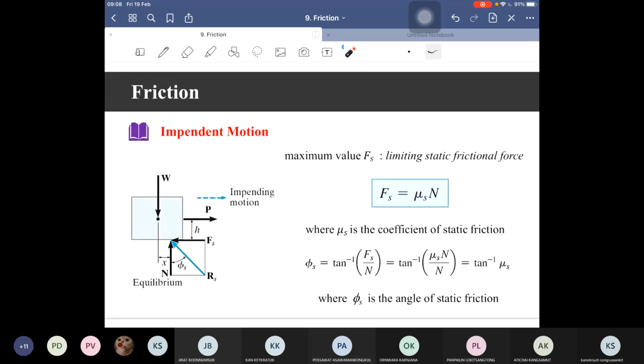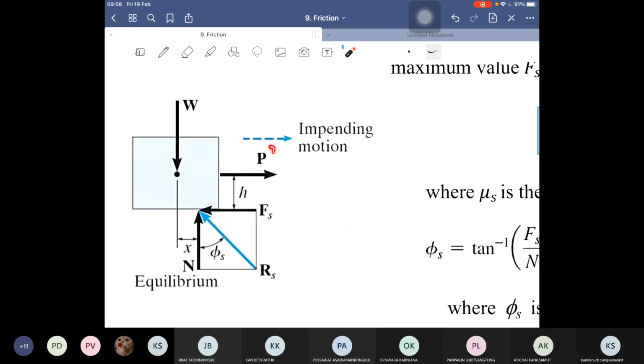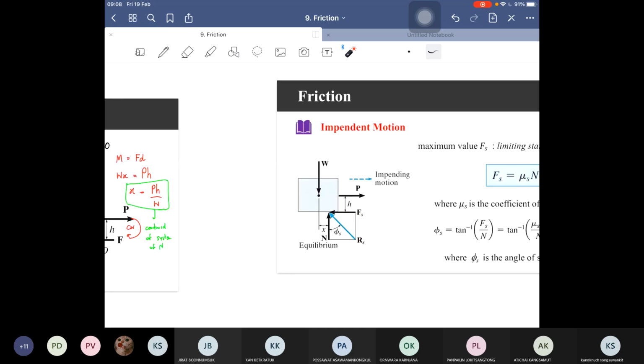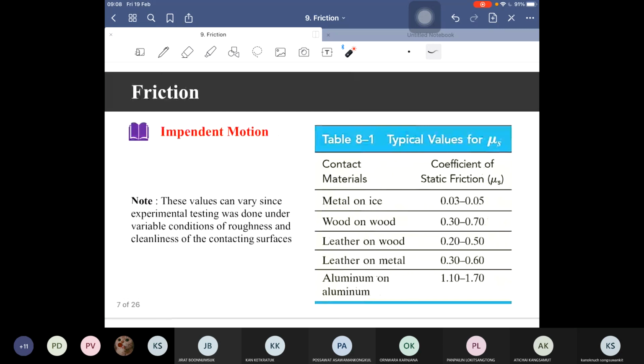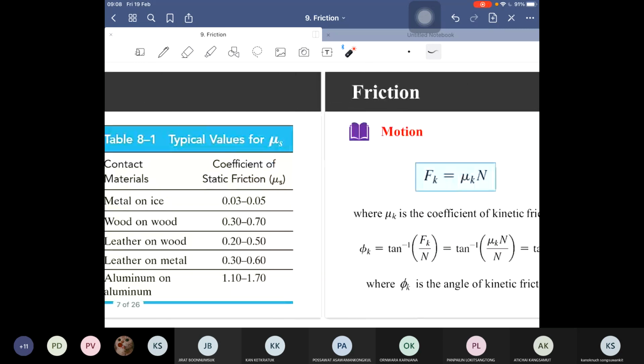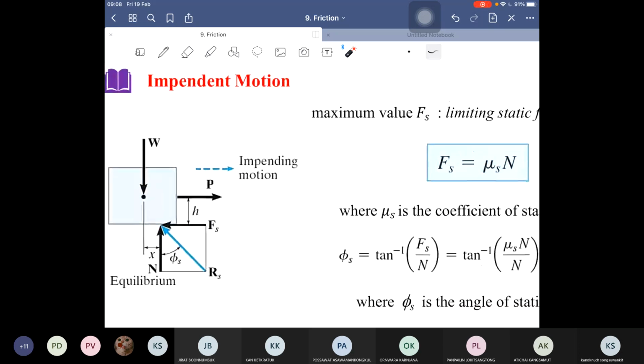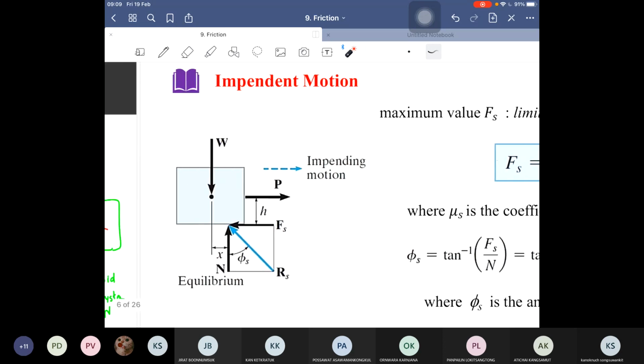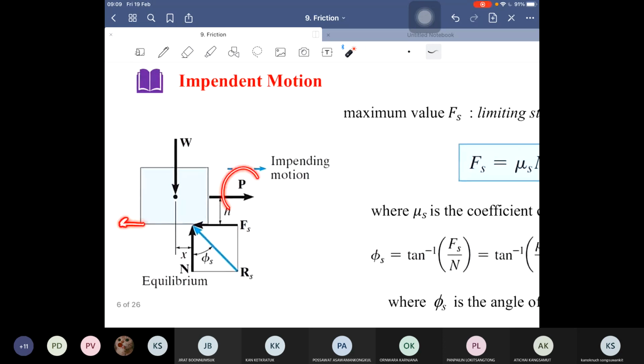Okay, so while you are increasing the force P and trying to move this box, there are three possible states: impending motion, motion, or statics. Okay, in the case where the contact surfaces are slippery, the frictional force F may not be great enough to balance P, right?